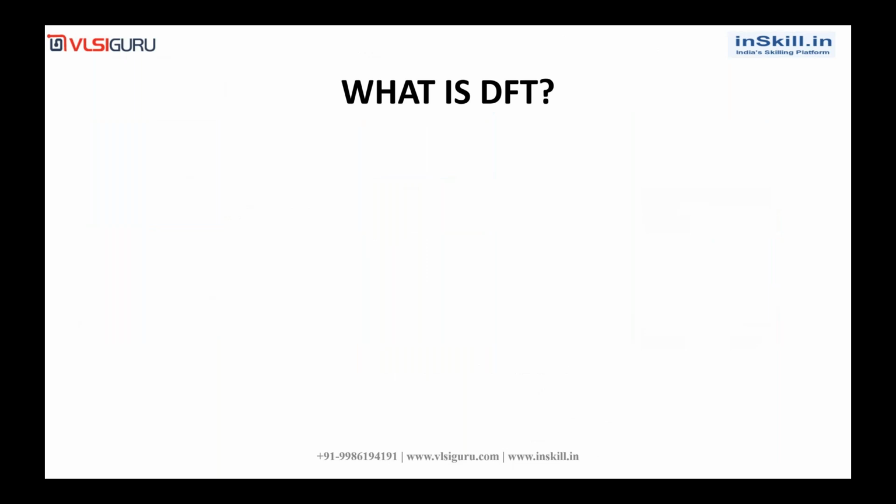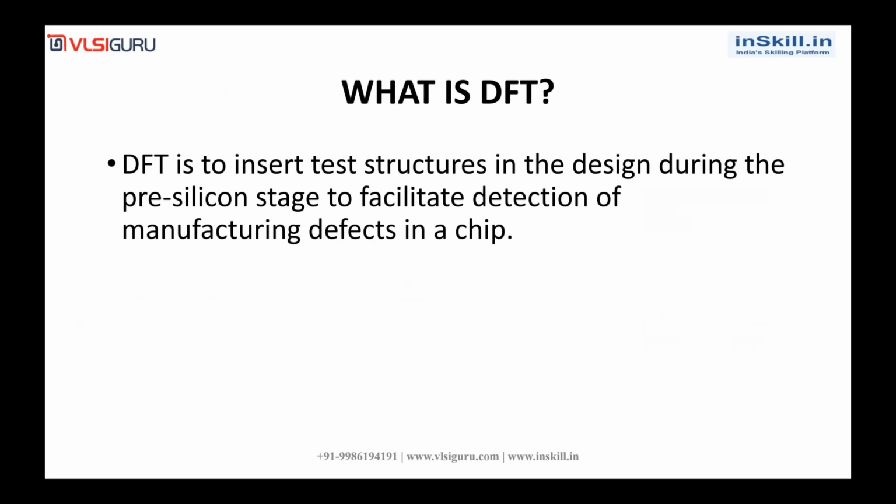Now we will try to understand what DFT is. As I told in the previous slide, the definition is that DFT is to insert test structures in the design. We will be adding our own test structures in the design, like scan insertion, MBIST insertion, boundary scan insertion, during the pre-silicon stage. Pre-silicon stage means before manufacturing.